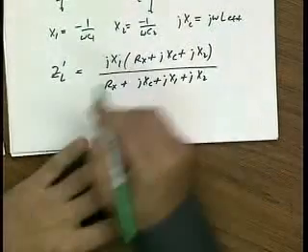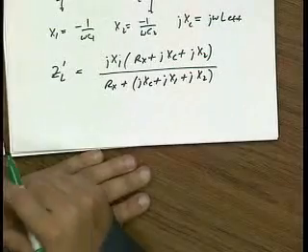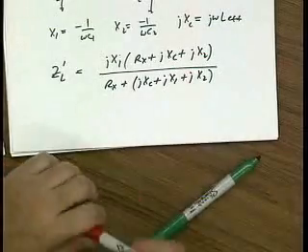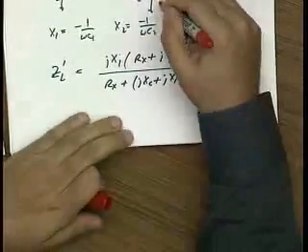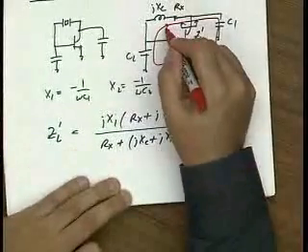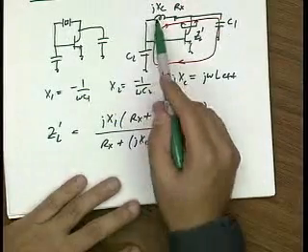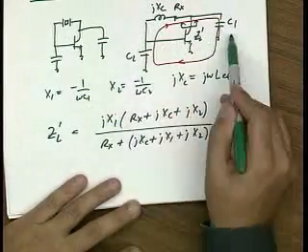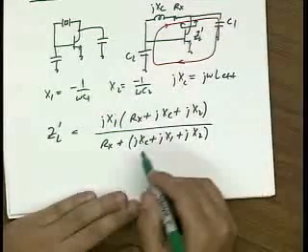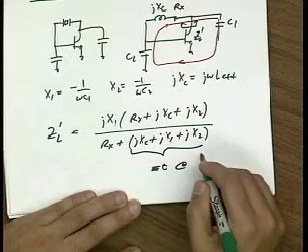Right? Well, this denominator term is quite nice because in resonance, remember, where's the resonant current flowing? Resonant current flows in this loop. That means that this element, jXc, is in resonance with a series combination of C1, C2. So all of this is identically equal to 0 at resonance.